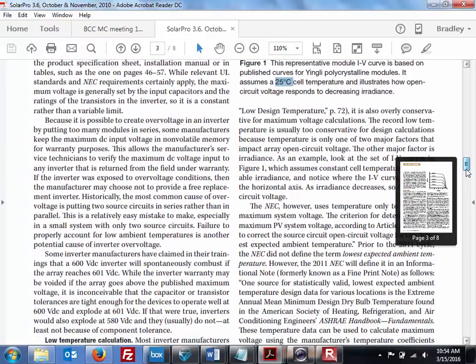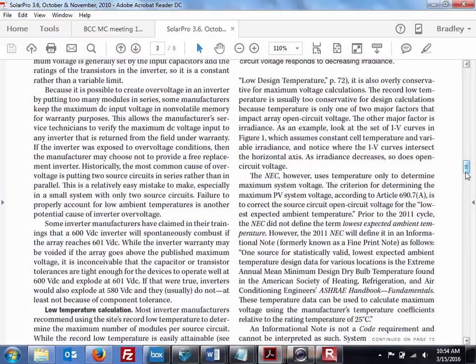Do most cells include an optimal operating temperature as well? Well, the standard is 25 degrees Celsius, and so that's what they're rated for. And to my knowledge, every single array is going to become more efficient when it's colder and less efficient when it's hotter. It's not going to be linear necessarily, but I think it might be maybe a 1/10% per degree is about the efficiency.